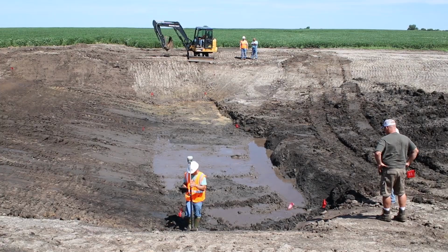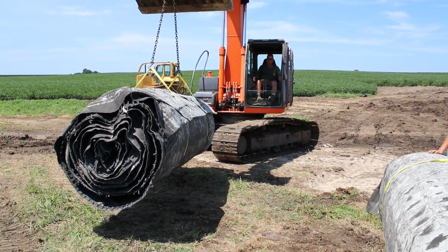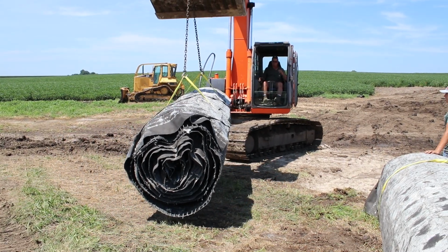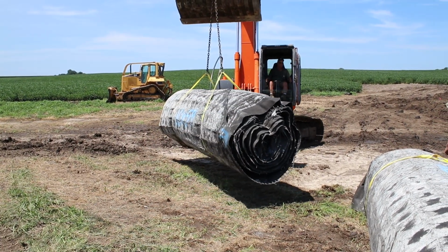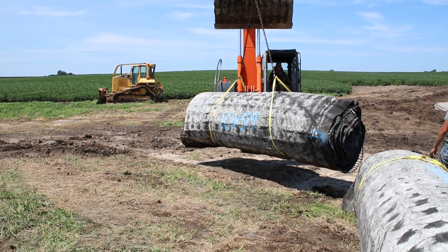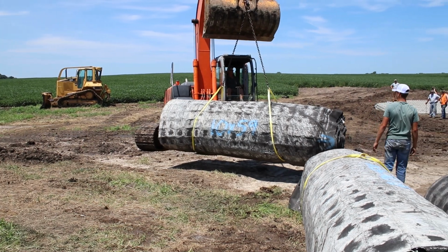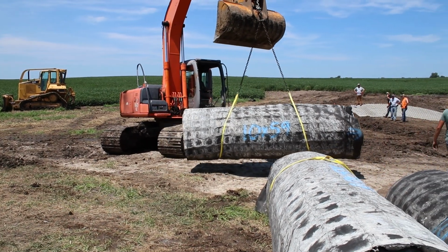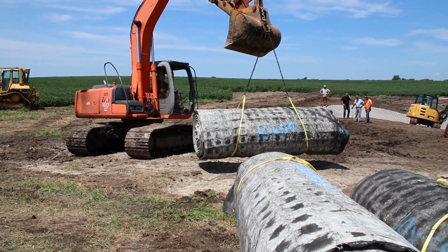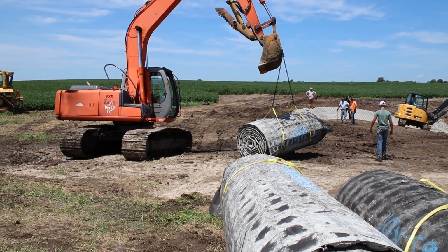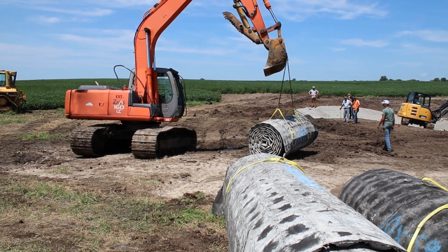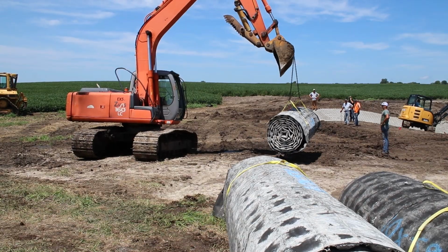The tied concrete block mat, as you can imagine, is heavy, about 10 pounds per square foot. One roll of this structure would weigh over 3 tons. Heavy-duty lifting straps make it possible to pick up the rolls from above. Lift straps come ready for use with each roll and eliminate the need to pick up the rolls from below, which would risk damage to the integrity of the mats.